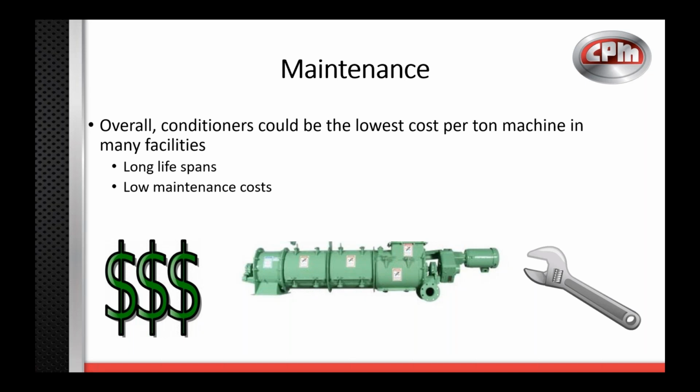One thing to also consider is if you are running a certain capacity and you want to extend your retention time, which might mean going to a bigger conditioner, essentially the capital cost is the only factor you have to take into consideration when going to a larger conditioner, because in the end, you're still running the same capacity. You've just gone from 30 seconds of retention time to 60 seconds. So it's something to keep in mind.